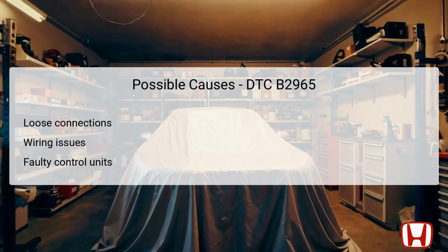Lastly, a malfunctioning rear AC control unit or HVAC control unit itself could also contribute to this error code being logged. Each of these possible causes needs thorough examination during the troubleshooting process to ensure all connections are secure and that the components are functioning as intended.